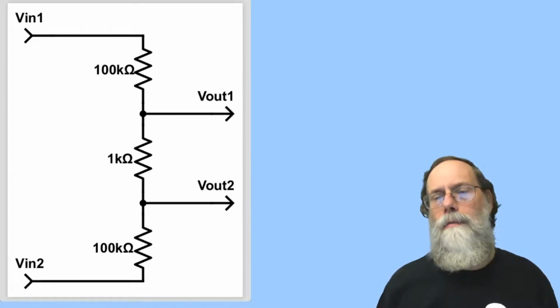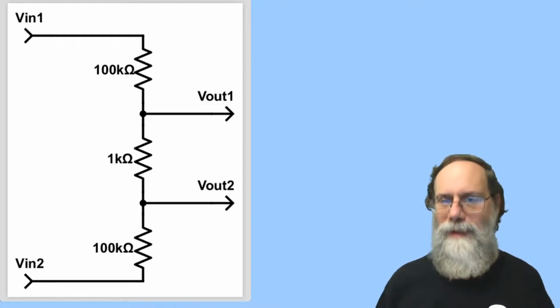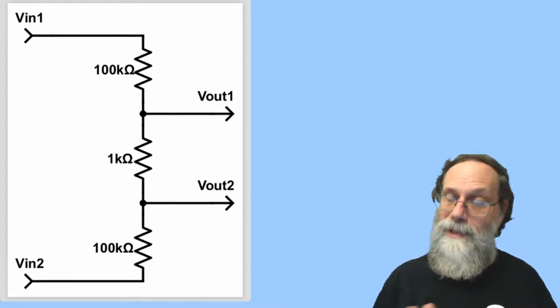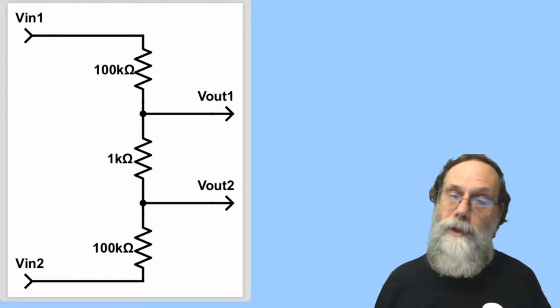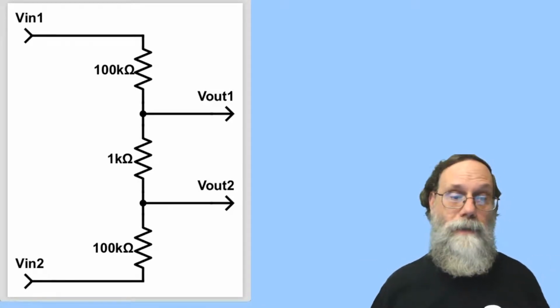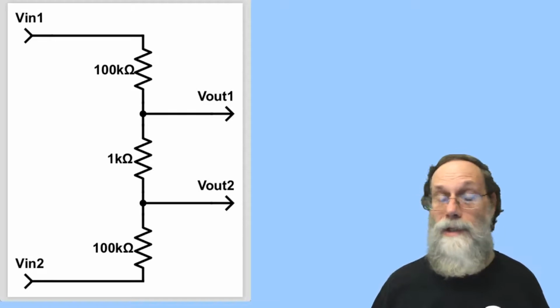Okay, so once you've built and tested stuff on your breadboard, basically testing one stage at a time, starting from the beginning and working towards the end, once you've got something that you think is working, then you need to hook up the EKG and test it with that.